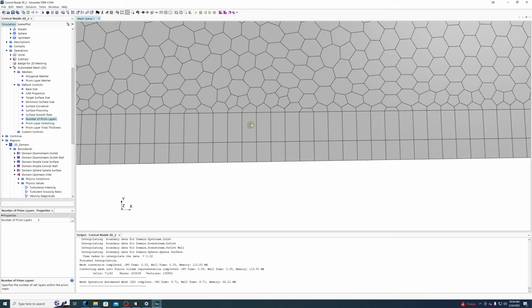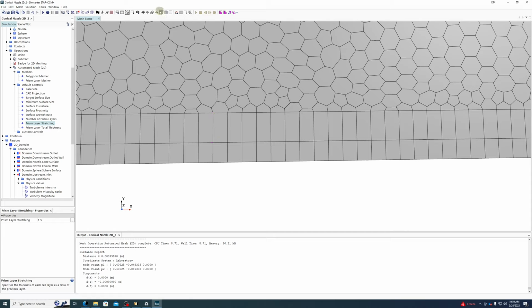Right now, we have three specifications. We tell it how many layers of cells there are. Right now, there are two. We tell it how big each layer is relative to the last. So 50% means this second cell should, in theory, be 50% as thick as the first cell. So this looks like it's about a millimeter, which means that first cell is probably pretty much exactly 2/3 of a millimeter thick. Makes sense. Checks out. The second cell is 50% thicker than the first cell.